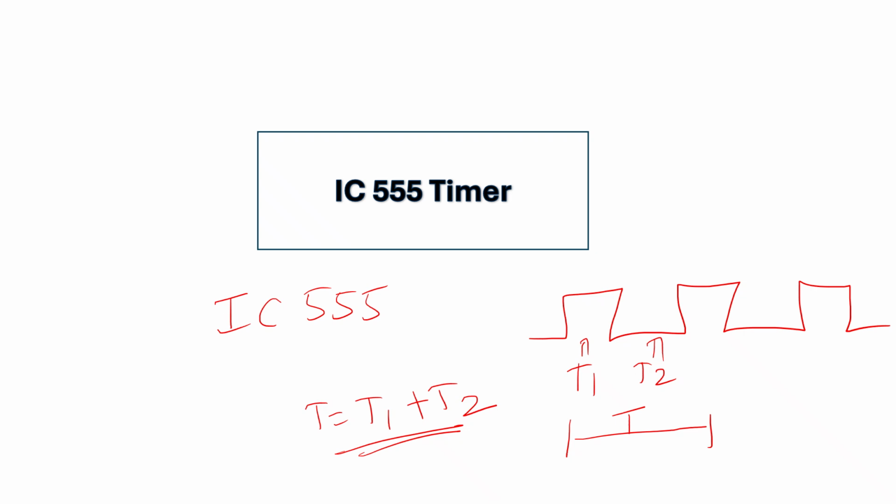So it is an 8-pin package with the grounding, triggering, output pins, reset pin, control pins, threshold, discharge, supply pins. I will draw the block diagram of the timer IC. So these ICs are used for generating square waves and hence for multi-vibrator circuits.